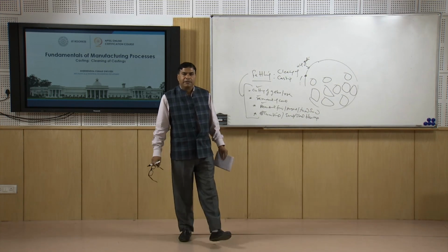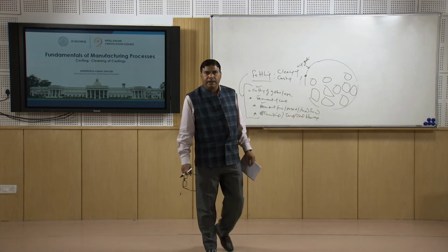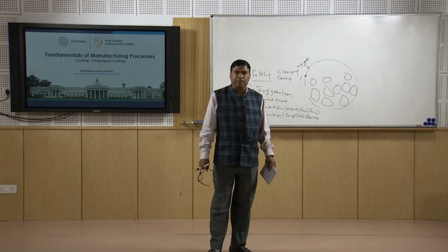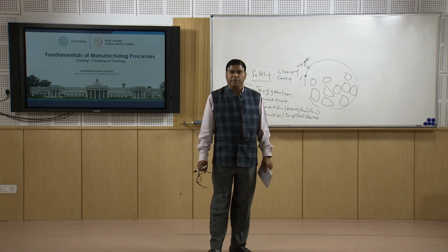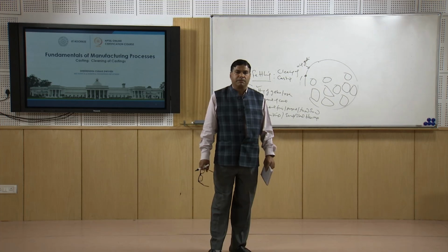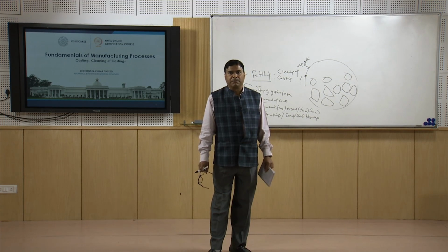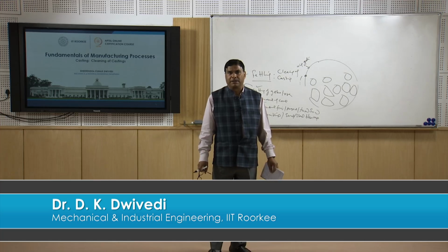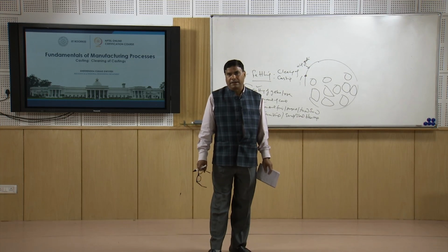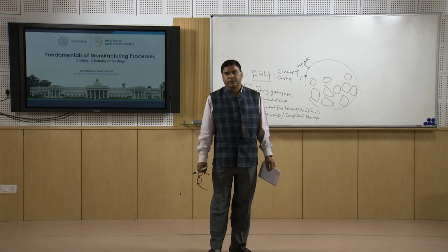So, now I will summarize the presentation. In this presentation I have talked about the temperature at which the casting should be extracted from the sand mold by breaking the mold, and once the mold is broken, then we need to remove a number of undesirable features which are present in the casting, for example the removal of the gates and risers, and removal of fins, projections and undesirable materials which are deposited on the casting surface, so that a clean and usable casting can be produced. Thank you for your attention.